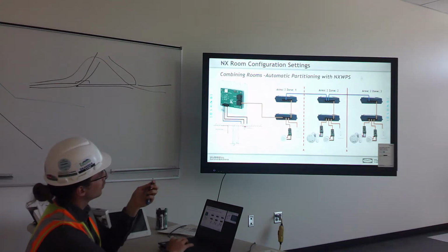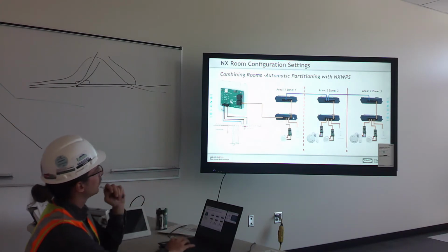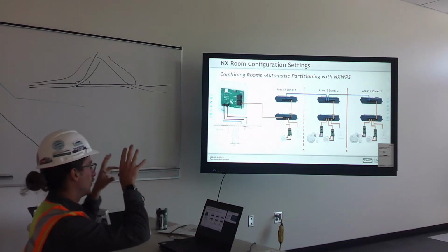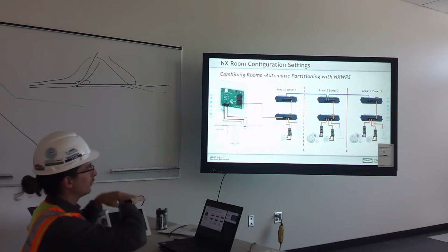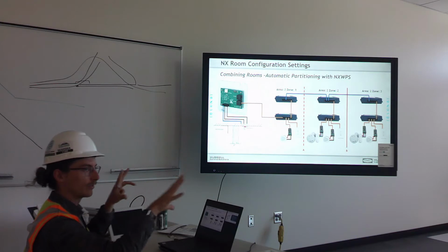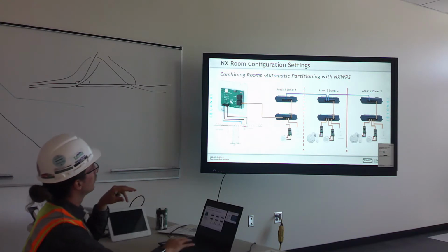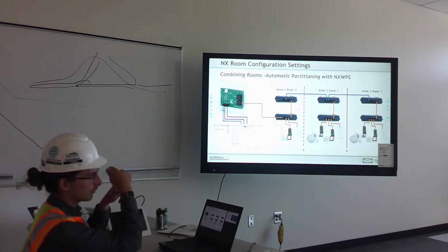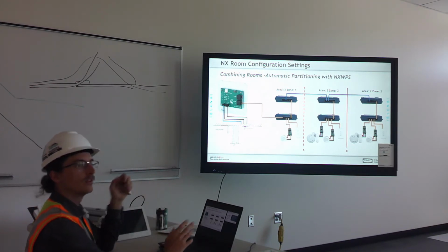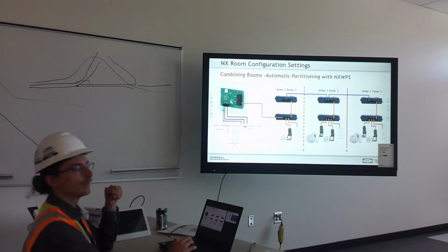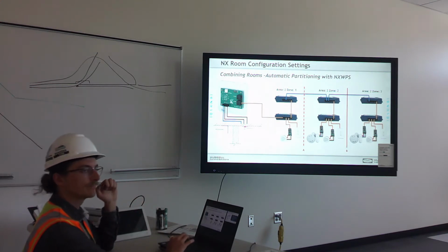So that both switches will control the entire room. This shows a setup if you had three different sections, but in that room we've actually only got two. You've got a set of room controllers in each room and a bridge in each room. Typically they would just work on their own, not talk to each other. But when this device sees that the beam is reflecting back to itself, open, it's one big room. And then the switches work like three-ways. You control all the light from either switch. Exactly. When the wall's closed and the beam's broken, the switches turn into single poles for the individual rooms.